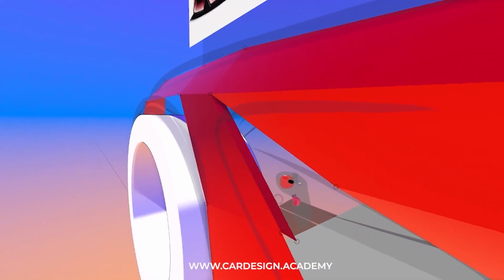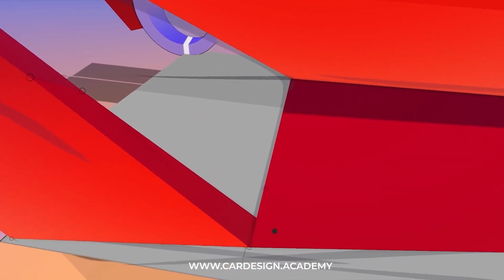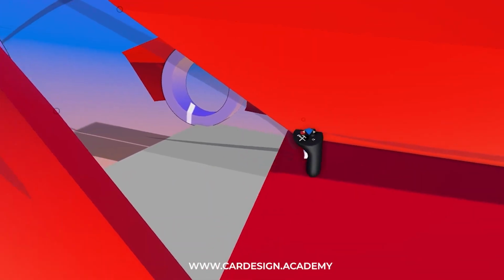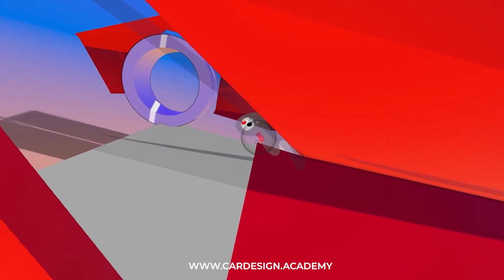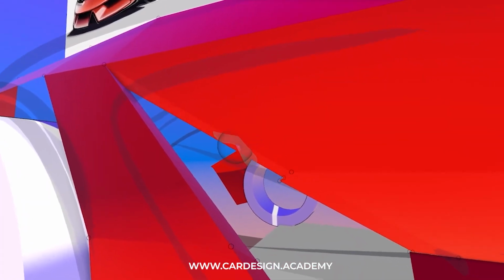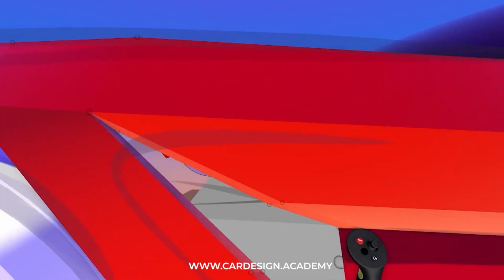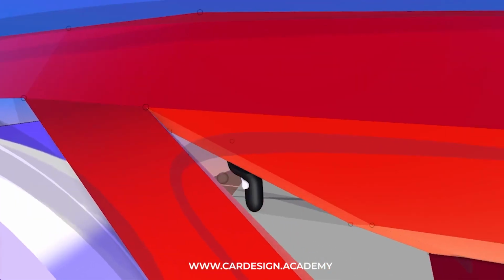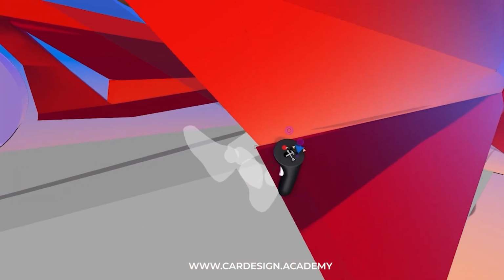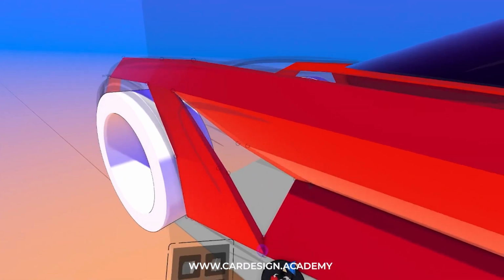One thing I like to do with these sort of scoops and intakes is to put a bit of a mitered edge around it. You can see how the points just automatically snap to each other. If you were to try to weld points and vertices together in most other sub D modeling programs, you usually have to go through a series of menus and clicks. Whereas here you can do it very, very quickly and intuitively.